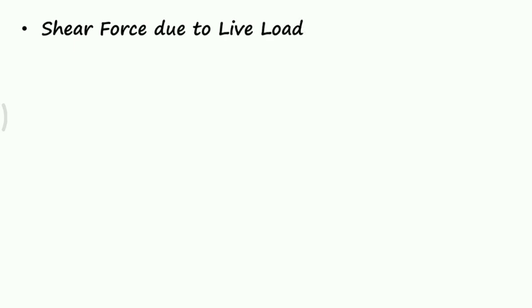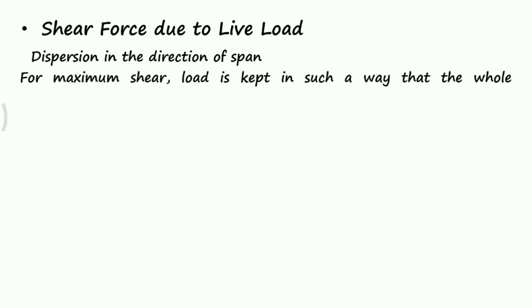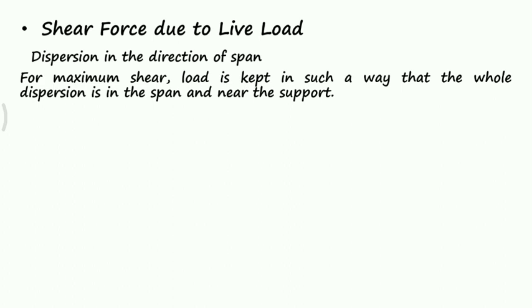Next is the shear force due to live load. As previously, for maximum bending moment, we kept the track exactly at the center of the panel. Here we'll see the dispersion in the direction of the span. For maximum shear, the load is kept in such a way that the whole dispersion is in the slab and near the support. So as per IRC 21,